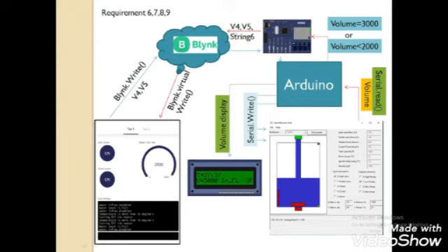These V4, V5 and string 6 are the virtual pins. V4 is for the inlet and V5 is for the outlet. Sending it to the cloud, with the same process, Blynk.virtualWrite, we are sending notifications that water flow is enabled and the water level is full.